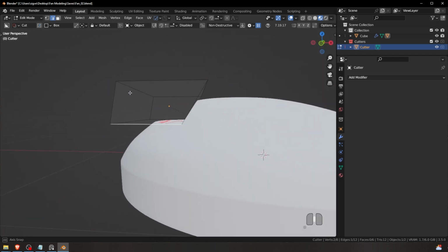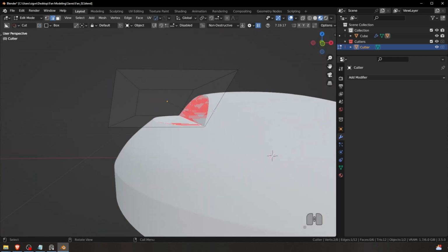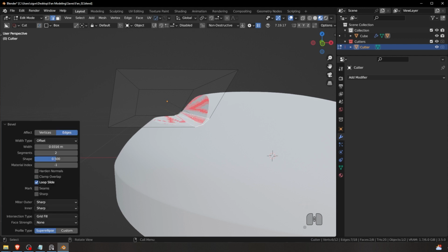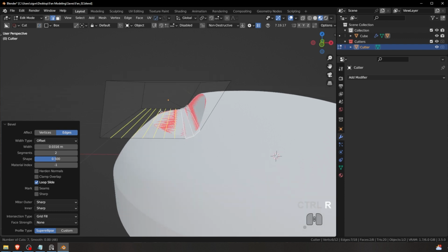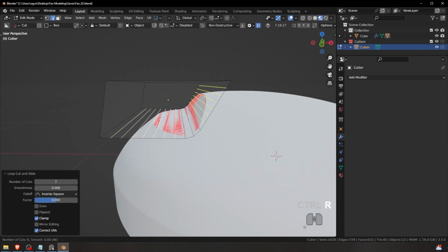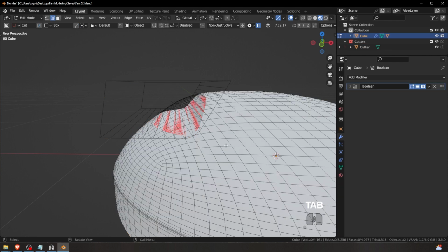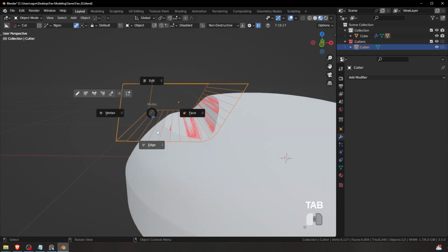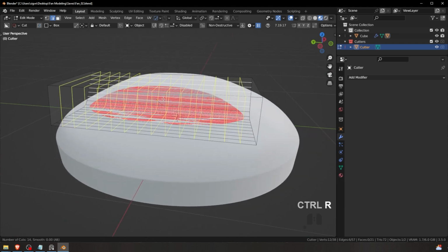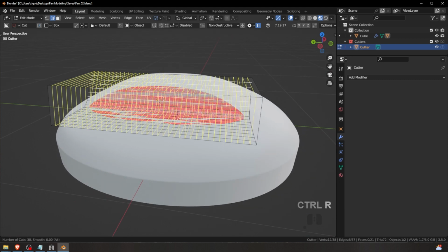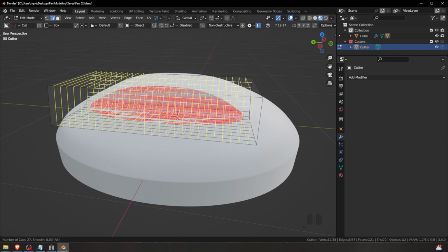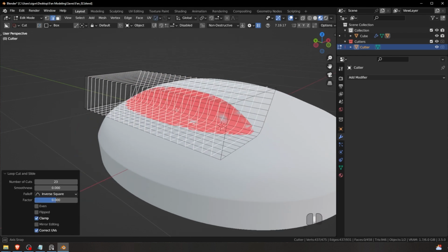Before we do that, maybe we do need a small bevel in here though. So just select this and bevel it with, I don't know, one segment, something like this. And now just add a lot of subdivisions in here. Try to keep similar density to this. You don't have to be very accurate, just kind of similar density. And in this direction, don't forget that you need to add loop cuts as well.